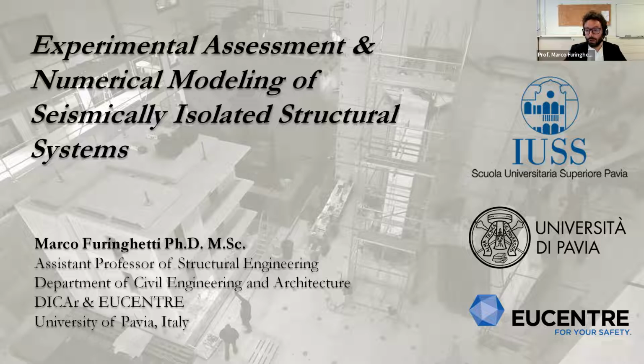This is very important because if the structure is already very flexible, so the stiffness is very low because maybe it is a high-rise building, or there is soil structure interaction with soft soil, maybe there is no need for seismic isolation. This can be assessed directly through the computation of the minimum value of a period to design isolation systems.